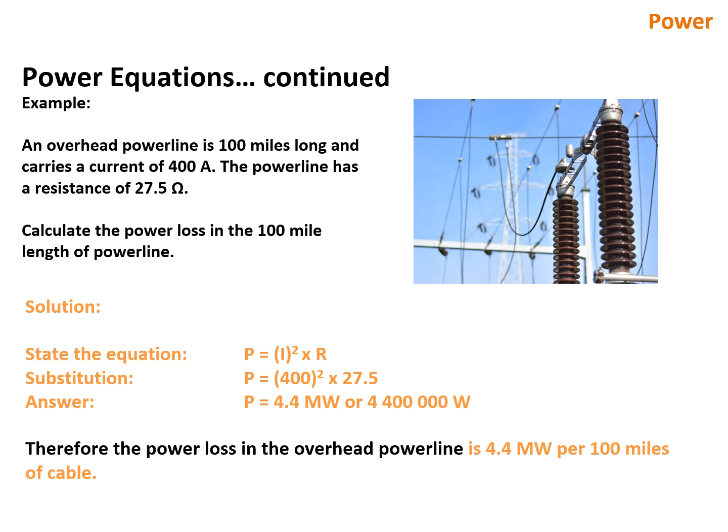Different power equation. Power is current squared times resistance. Different way of working it out. Remember, you've got the equation sheet. They will give you figures. If they give you the resistance and the current, you know to use this equation. Whereas if they gave you voltage, potential difference, and current, you use that equation. They might give you the information to work out the resistance for this first one, and then you use the resistance.